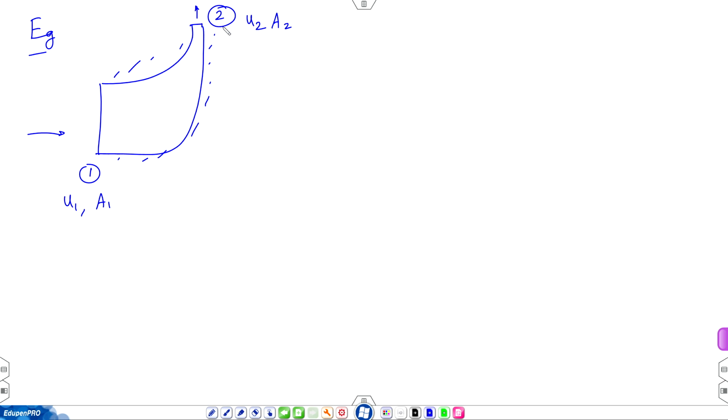If you look at numerical problems given in the book, the forces turn out to be substantial. So, you can always think of your hostel, and wherever you see a bend, suddenly be alarmed. There is a bend over there, we have to be careful. Okay. So, of course, you have to apply force on the fluid to turn it around. Equal and opposite will act on the tube, and equal and opposite will act on the support that holds the tube in place. So, if there is any fluctuation in flow, that will induce a time dependent force on the bend, and you may have seen those bends moving quite violently,